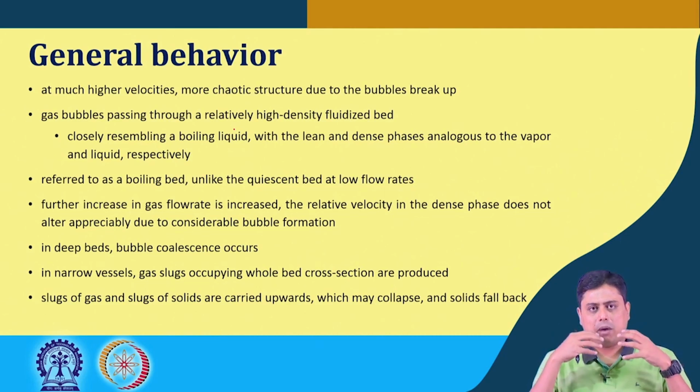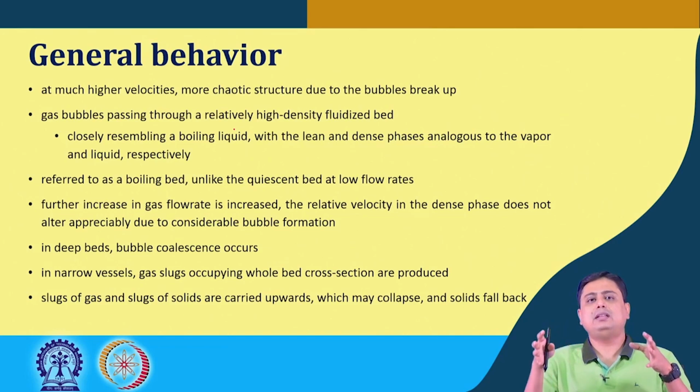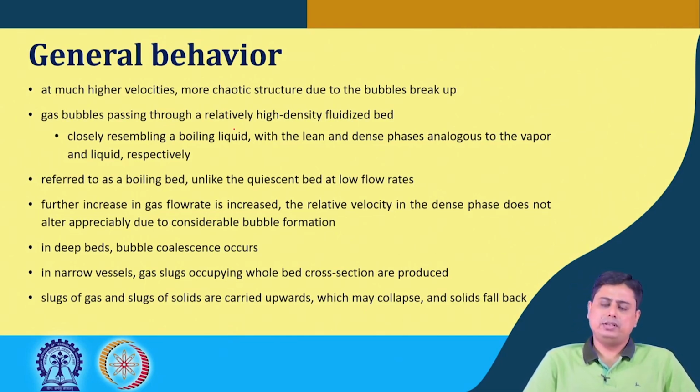So, when the gas bubble flows through a relatively high density fluidized bed, we find an analogy of such flow phenomena with a boiling liquid, where the lean and the dense phases you can relate to the vapor and the liquid phases respectively. So, as if some boiling of liquid is happening, or the gas bubble forms and breaks and creates chaotic motion inside that gas-solid fluidization, and this we refer to as the boiling bed.